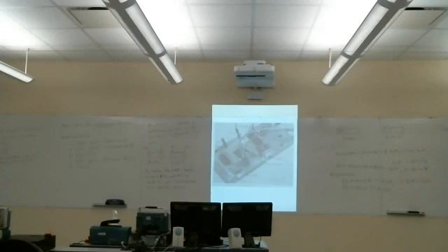The debugger that we use with Code Composer Studio can actually connect directly with this debugger chip, and we can examine register values within the microcontroller itself and see exactly what's happening.